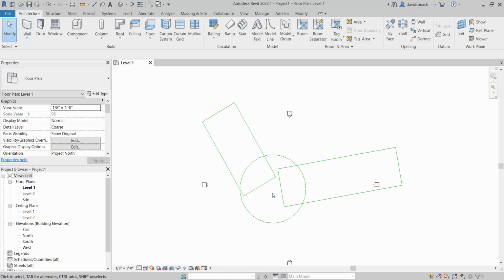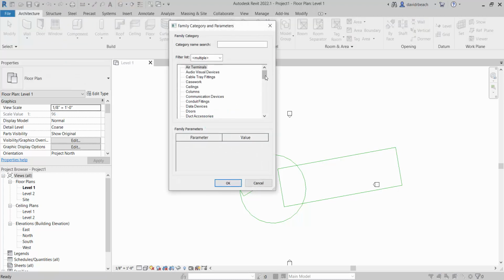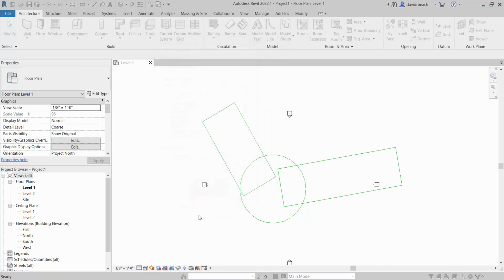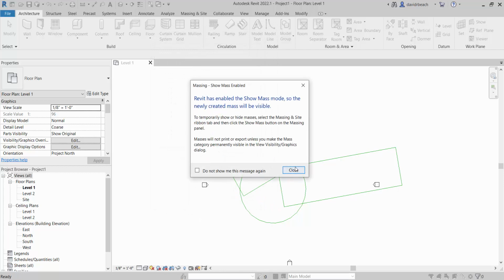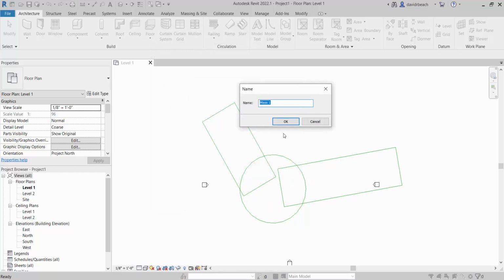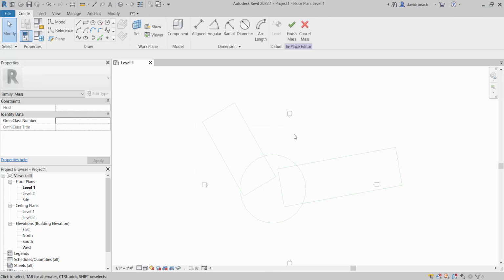One of the best ways I think to do this is using the component model in place and custom massing tool set with three-dimensional splines. So that's what I'm going to walk through, and then we'll be converting that massing form to a roof by face. So in the conceptual mass setup inside of Revit, it works different than the generic component or anything else.